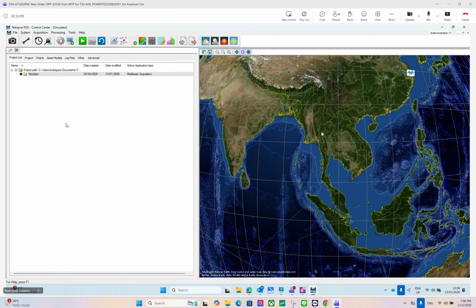So if you consider this, position arrives at the primary antenna at the L1 phase center. Then through your lever arms, you will take position and transfer it to the IMU. So, for starters, you've got to get those lever arms accurate, because the longer those lever arms, with less accuracy, the worse the error is going to become. Because the boat moves, the antenna moves around.